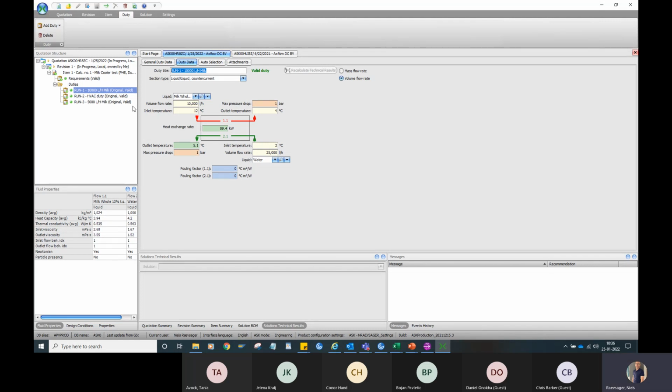There are two ways of doing that. There's either pressing this one. If you do that, you automatically jump into a dialog called Auto Select Cheapest. That one is fine if we're talking about water heat exchangers. Then it will give you a reasonable design based on price.